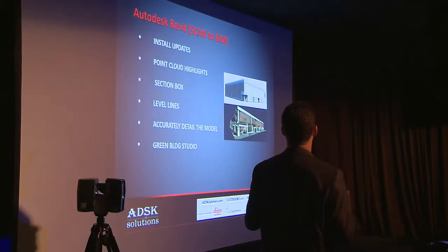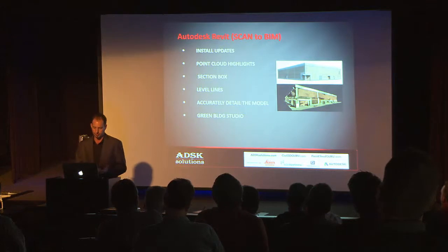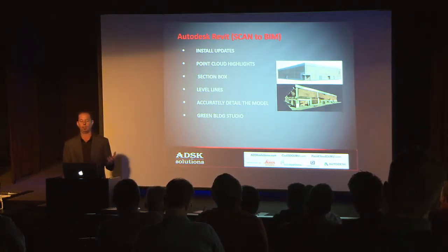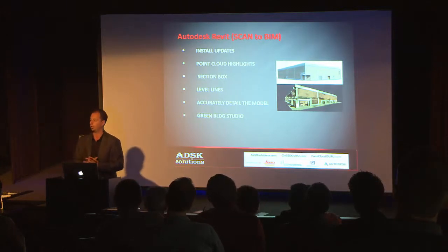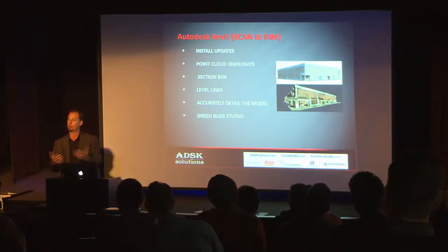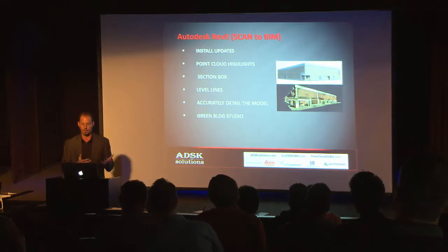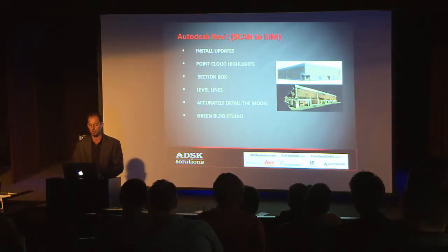I want to talk a little bit about scan to BIM. What I liked about this as well, if you're using Revit, I don't know how many people are using Revit in here? Is there a few? Okay, yeah, pretty good amount. So hopefully you brought the point cloud directly into Revit, which is nice. So you bring in the Recap file, the RCS, RCP, to load the multiple scans directly in here.